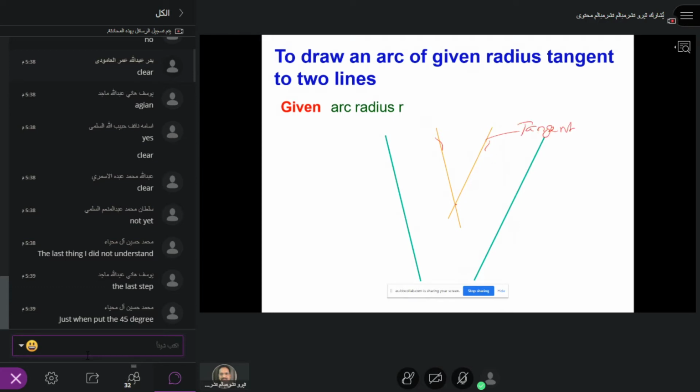And now you have to draw the perpendicular line from there. So how to draw the perpendicular line? This should be 90 degrees. Okay, this is the line. So this is another line, and it should be 90 degrees. So how can we make it? Again, we are using the tri-square, parallel, and just move it. Now you see, this is 90 degrees.